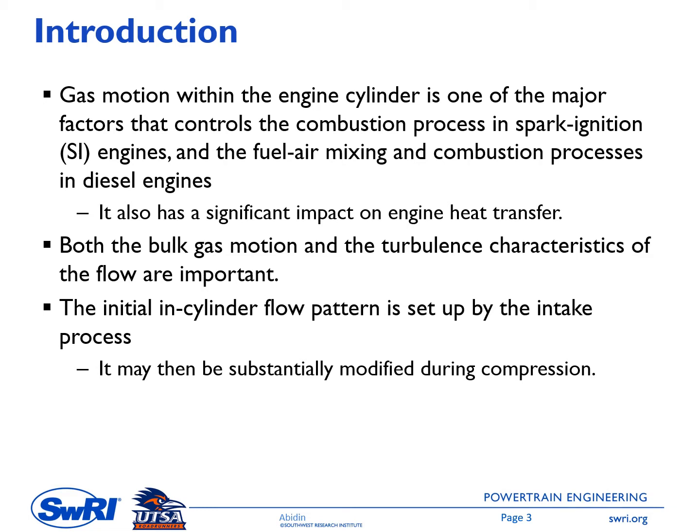So we have a certain bulk flow pattern during the intake stroke, and then as the piston moves up toward top dead center, some of this bulk flow might be converted into a different flow pattern, and the ultimate goal is to have high turbulence at the end of the compression stroke.